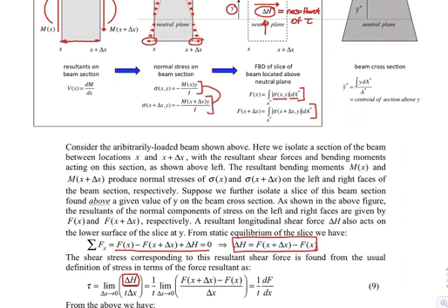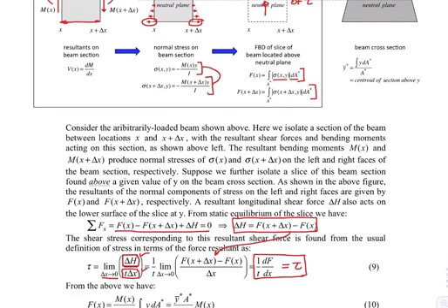If I divide by the area over which it acts, it's delta X in X, t is the dimension back there in Z. So this is basically force divided by the area over which it acts. We let delta X go to 0. We use our result there from above, and we get that tau is equal to 1 over t dF dx. It's an important equation, but not one yet that we're ready to use.